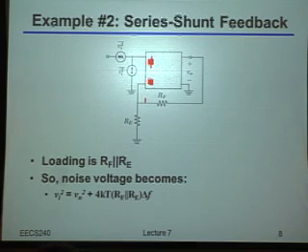Okay? Well, if you think about the loading from a voltage standpoint looking back from that terminal, what you essentially have is this RE in parallel with that RF. Right? That's the equivalent source impedance of that divider there. Okay? So just like before, we would say that, at least approximately speaking, the voltage noise due to that feedback network would just be 4kT times RF in parallel with RE times delta F. Does this make sense to everybody?